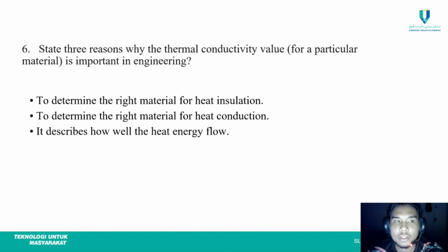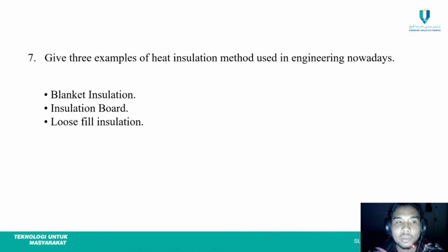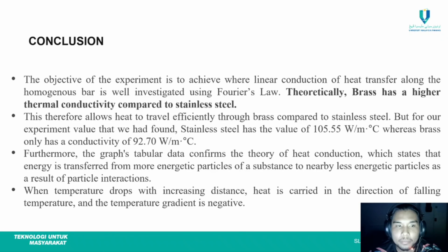For question number 6, state 3 reasons why the thermal conductivity value for a particular material is important in engineering. First, to determine the right material for heat insulation. Second, to determine the right material for heat conduction. And the third is to describe how well heat energy flows. For question number 7, give 3 examples of heat insulation methods used in engineering nowadays. First is blanket insulation, then insulation board, and loose fill insulation.